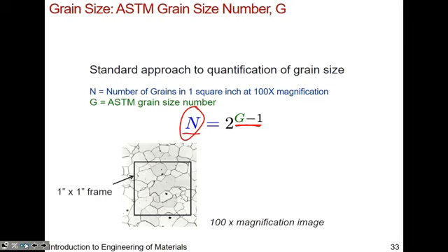Okay, right. So we left off on the discussion of ASTM standards and also how do we quantify the grain size number and also the number of grains. Clearly you can see from this micrograph that polycrystalline samples have different size grains. And of course we try to engineer them to be as uniform in size as possible. But of course there's always some distribution, and so we talk about the material using this grain size number, and it's related using this equation that you see here.